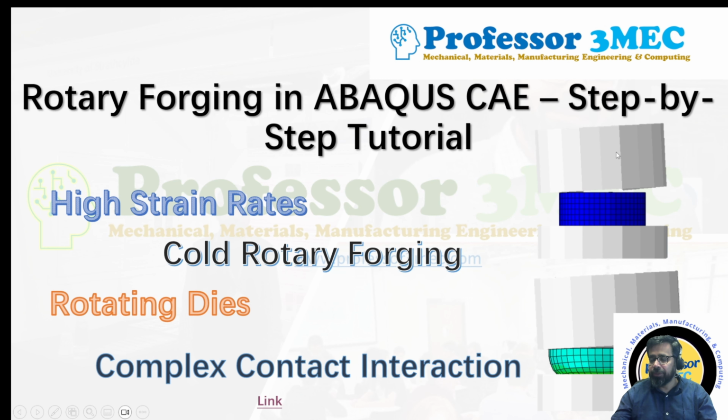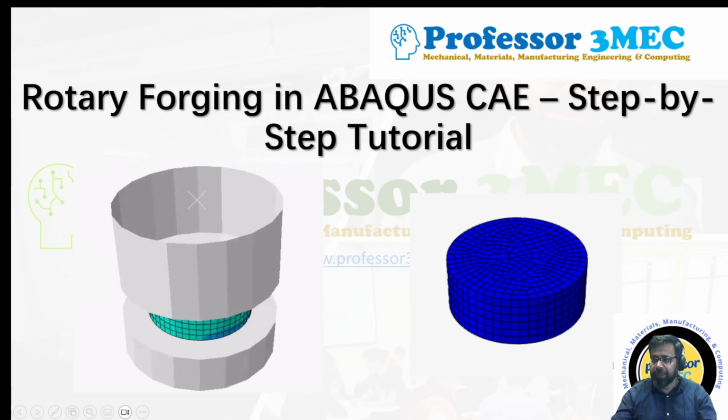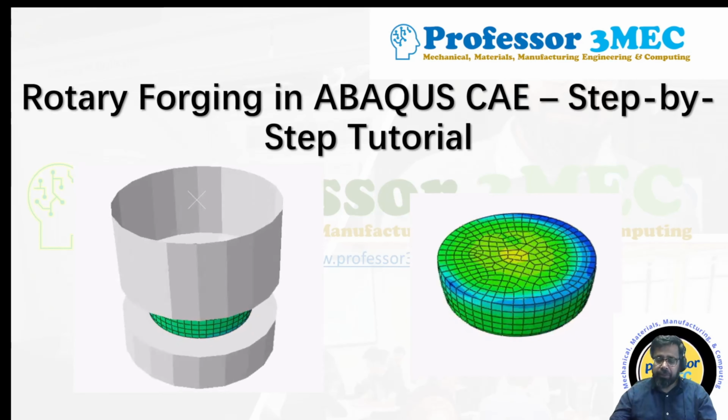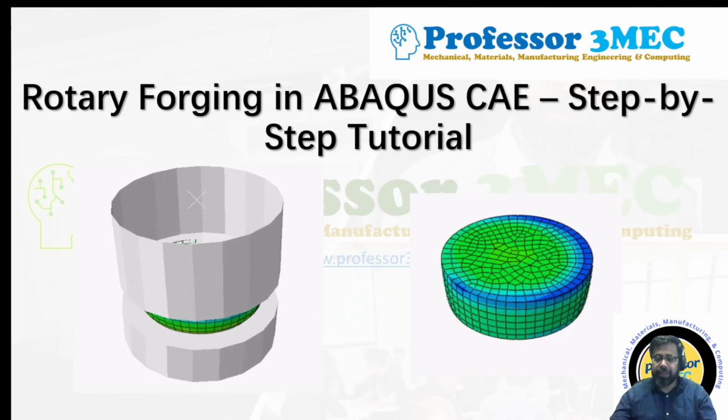I have a top die, as you saw just now in the video. We will have a bottom die, a workpiece. Both will be rotating, and then this die will be at a certain angle with some conical shape. You can have any shape as you like for the part to be manufactured. Then we will use ABAQUS CAE to cold forge using the rotary forging process and form it into this kind of shape as you see on the screen. So at the end of the video, you will be able to learn this process. This is the animation of the process where we are performing cold rotary forging using ABAQUS CAE. So let's jump into it.